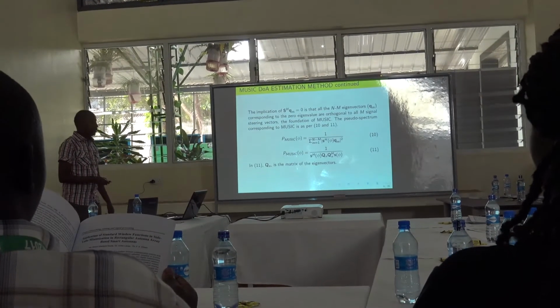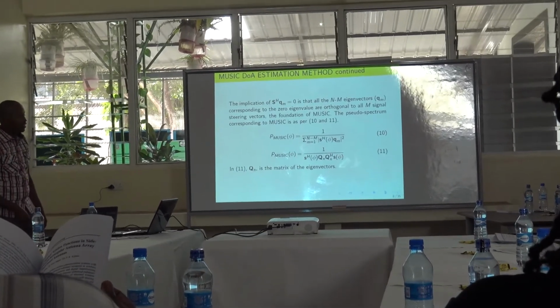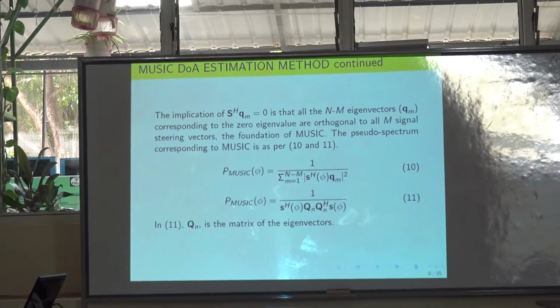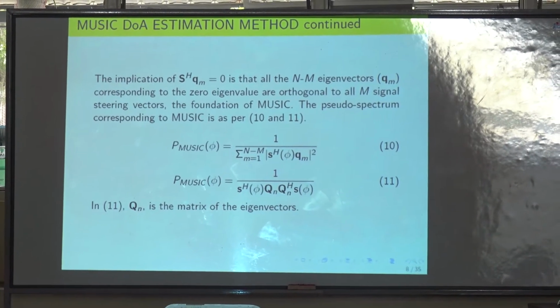Starting with a brief explanation of the MUSIC estimation method. The very first equation is for a linear antenna array of n elements. That expression consists of the signals themselves, whereby the symbol alpha is taken into consideration for m incoming signals, with n elements in the antenna array. The S over here is indicative of the array response towards those incoming signals, plus an addition of noise.